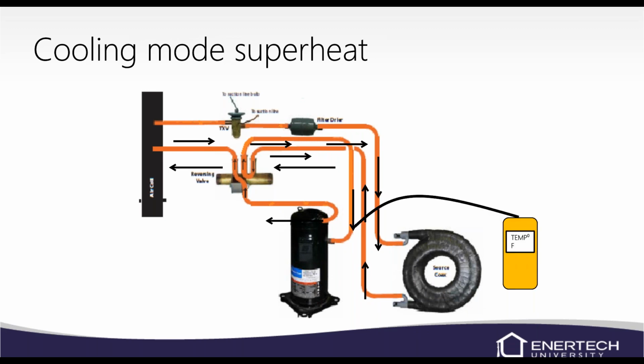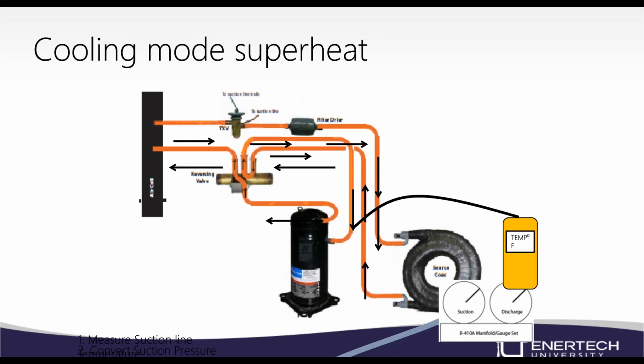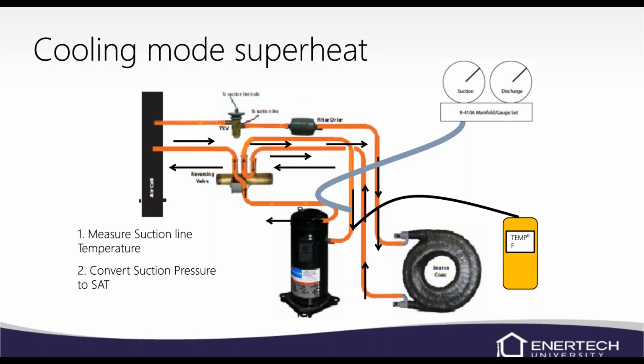Cooling mode, again, it doesn't change when we're in heating or cooling. It's still a foot off the compressor, and we're converting suction pressure to saturation temperature, and then we're just doing the math on that.